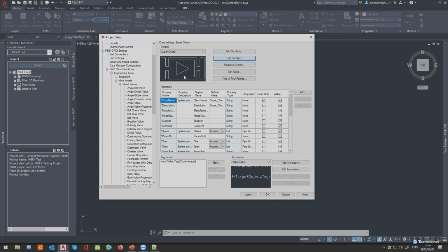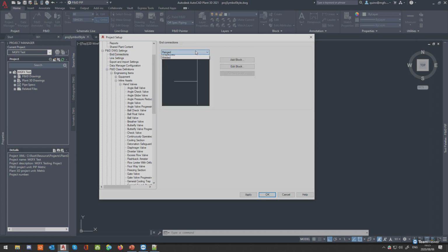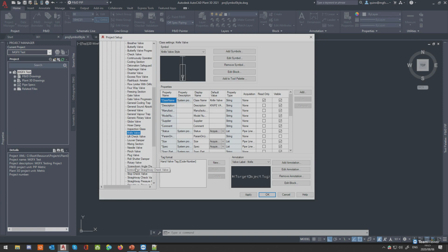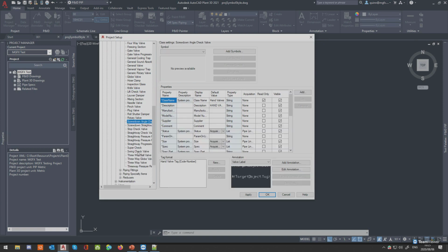For instance, if you get the symbol scale incorrect on one of your valves, it could be that when you're putting your end connections on, so let's say your flanges, sockets, etc., these don't scale properly, and you'll end up with your end connection looking really small or really big, depending on how you've messed around with this. So that's why one of the temptations with a lot of people when they start implementing this is they'll try and change everything to a scale 1:1, which if you're willing to go through the entire system and then change it to work like that, then cool.